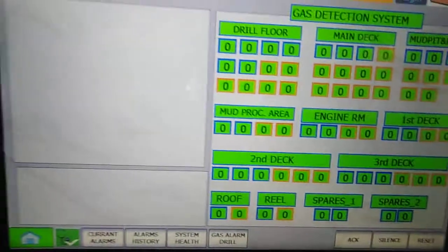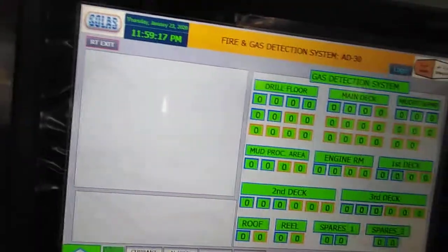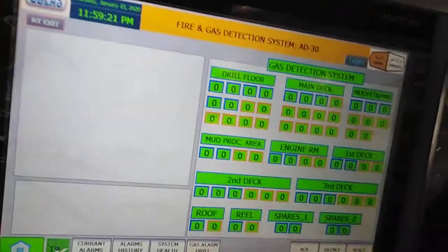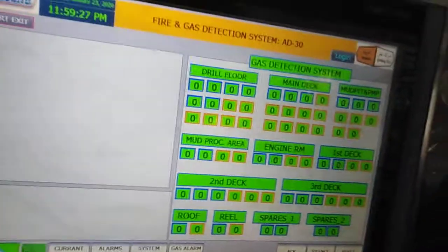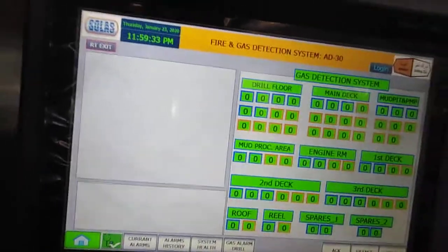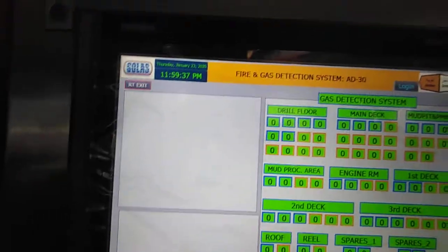Any administrator can make any configuration from the HMI. It means that when we add any new fire detector, we can add it from the HMI itself. So on that HMI, the page will contain the loop diagrams. From the loop diagram itself, we can select whether it's a call point or a detector, whatever it is. So it's just an overview of the system.